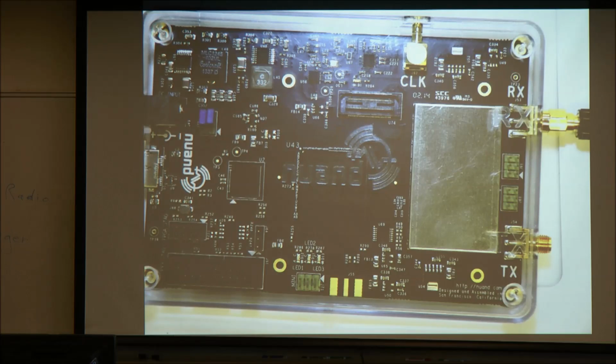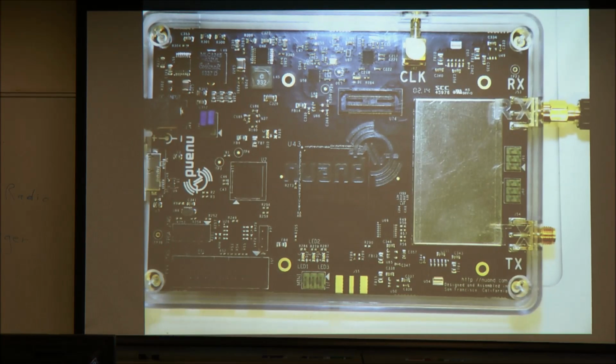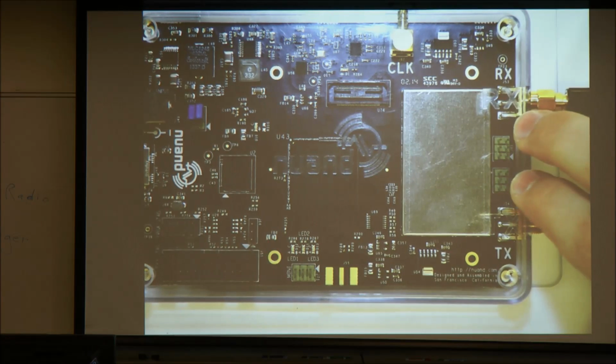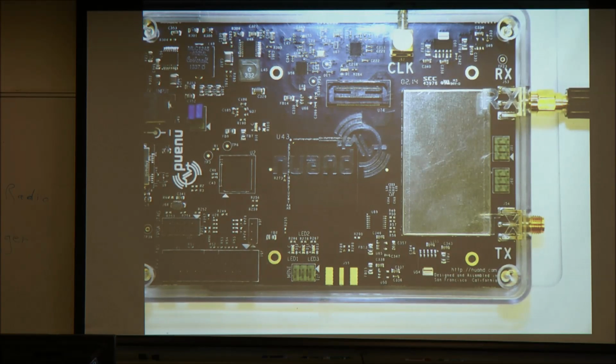So with the BladeRF, it only goes down to about 300 megahertz, which isn't low enough to go to the FM broadcast band. You can get a transverter board that plugs on top of this and has more mixers to downshift it. Now, there are also these headers here, and these headers let you go past the mixer and connect to what's called the baseband. And what that means is you connect to essentially right before the ADCs. So if you want to do really low frequency stuff, you could tell it to use the baseband and sample from there, but I haven't done that yet.